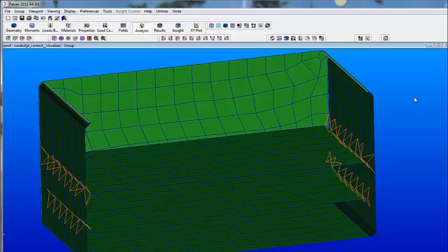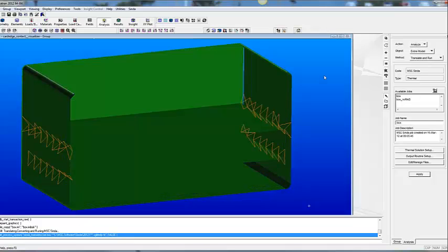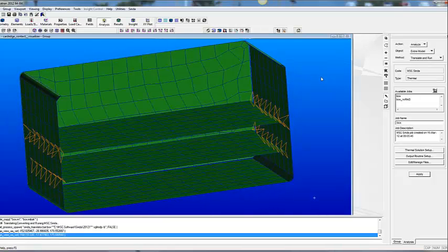And this model has venting, which was computed using one-way flow conductors, and we hand computed based on the temperatures what that updraft would be in pounds mass per second of the air. And if you would run this in a Flotherm or IcePak CFD sort of package, although you would have more information about airflow, you may not have any better answer than some of these hand-computed convection correlations, but it would take hours to run and not seconds.